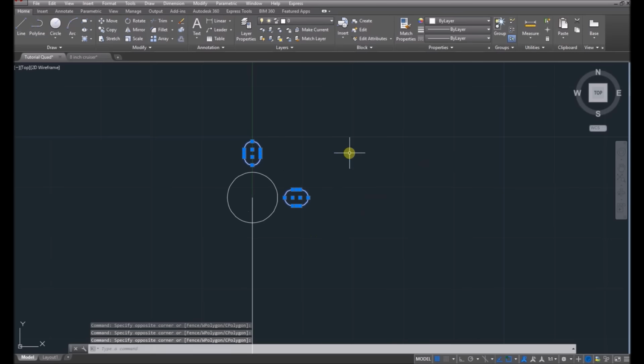Now when I'm selecting things, it's a little bit different to SketchUp because you select things and you just keep clicking on things and more things get selected. If you want to deselect, you click escape. That deselects. Right, so select those two, click mirror, click on that middle point again, and I'm going to go to tab and then 315 degrees.